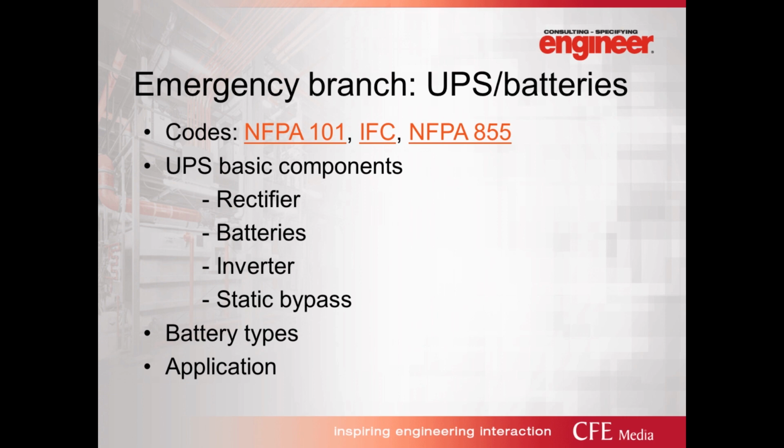The battery types used in the projects are typically flooded lead acid, VRLA, which is a sealed lead acid, or the lithium ion. The lithium ion batteries are getting more and more attention. Many projects are switching from lead acid to lithium ion batteries. The UPS are typically used for data centers, smaller telecom equipment, and security equipment.